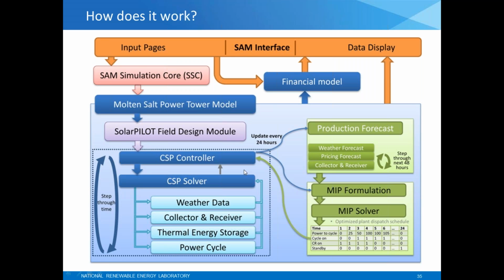The schedule will then be passed to the controller, and then the controller will go ahead and for the next 24 hours try to match the targets that were established by this approximate but sort of robust optimization solver technique. So it does that and it marches through the year. Essentially you solve this dispatch problem 365 times, once for each day of the year, and each solution corresponds to looking ahead a couple days and deciding what to do today.